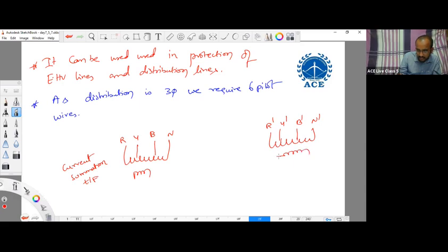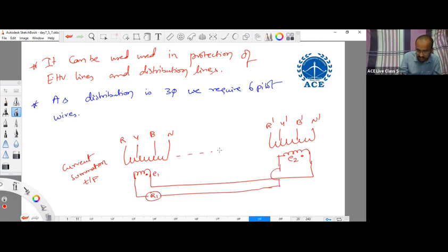Here there will be voltages induced, E2 and E1. Here also the same subtractive mode of connection is used. If you use the current summation transformer, how many pilot wires are required? Only two pilot wires, because here we are summing up all the three phase signals by using this current summation transformer. This type of protection is known as Translay relay type of protection. Understood my point?